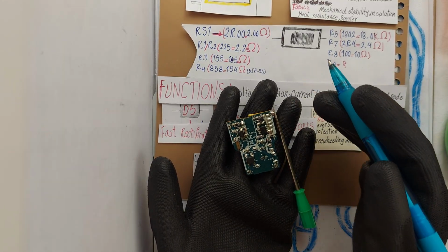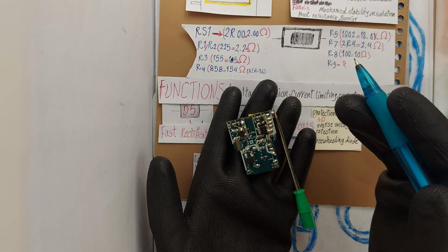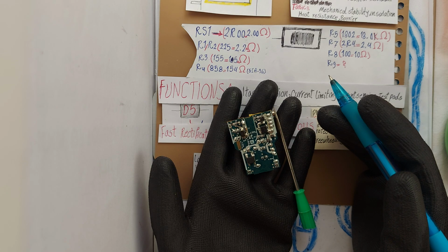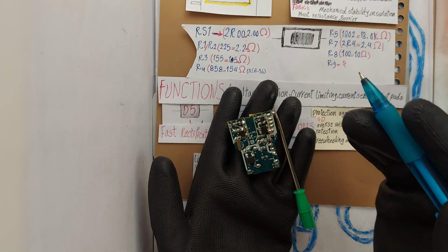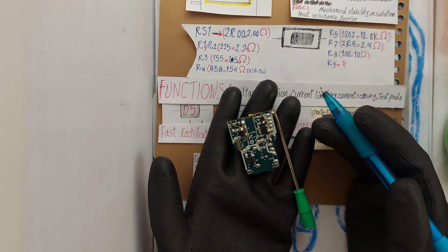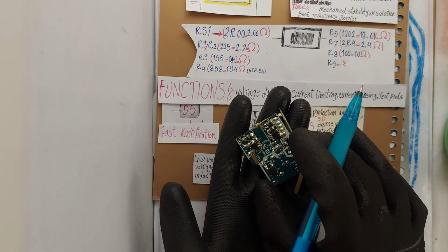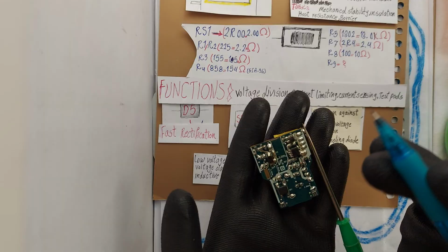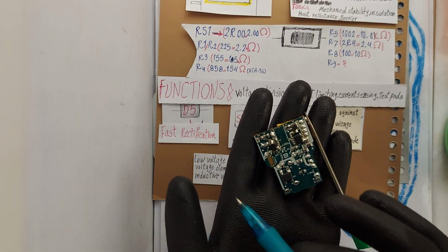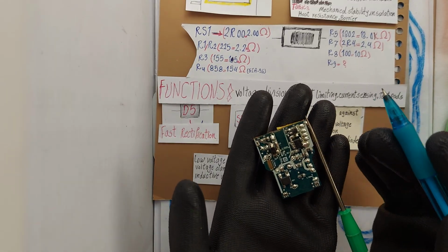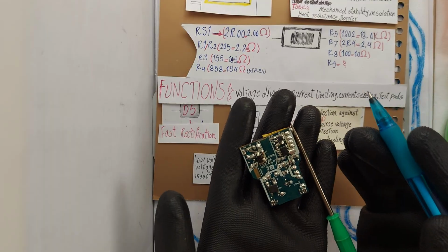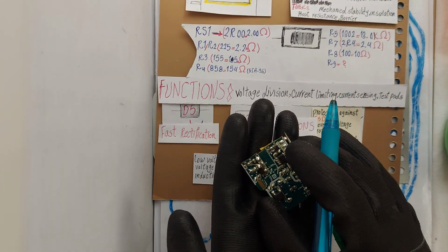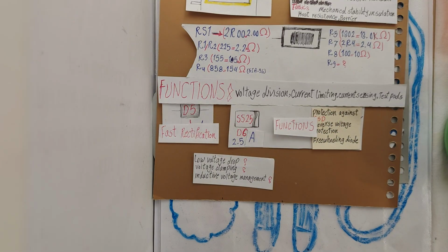Voltage clamping: a diode, or a combination with a resistor and capacitor, limits voltage to a specific level, directing excess voltage to ground or a safe path, especially to protect against inductive spikes from the transformer or switch. The position of D5 and D6 behind the transformer indicates their role in managing inductive voltage generated in switching converters when the primary coil current is cut off.